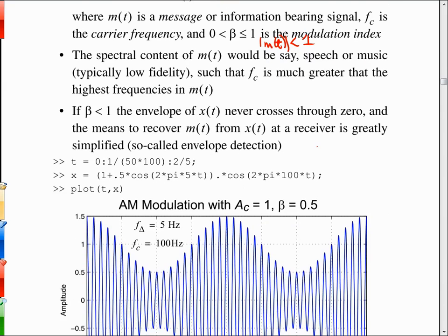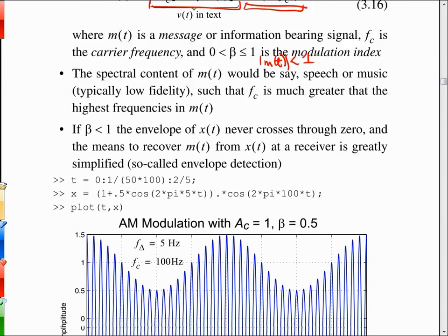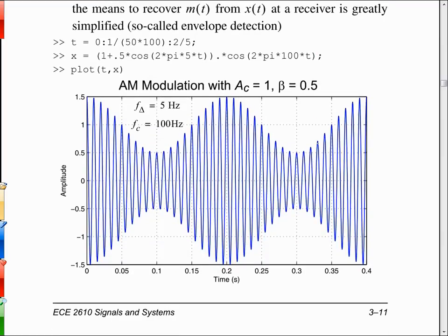So in the time domain, when you carry out this operation in equation 316, this is what the signal looks like. The high-frequency carrier, which would be at 850 kilohertz, not 100 hertz like it is here, would just be a very short duration or short period signal. And if we were looking at it in MATLAB, what would we be seeing, do you think?